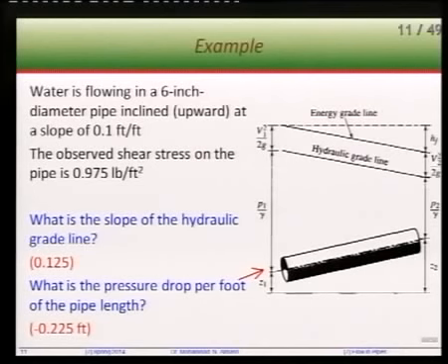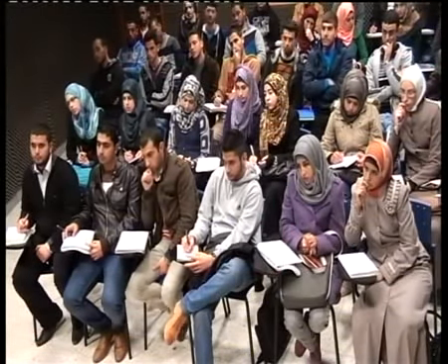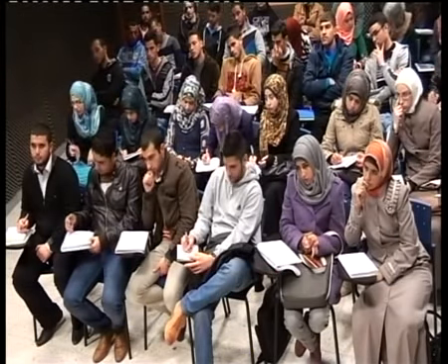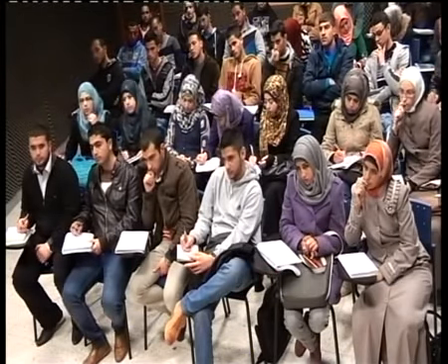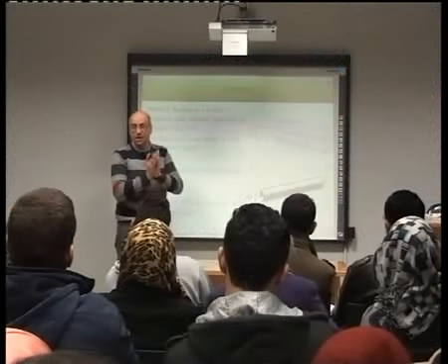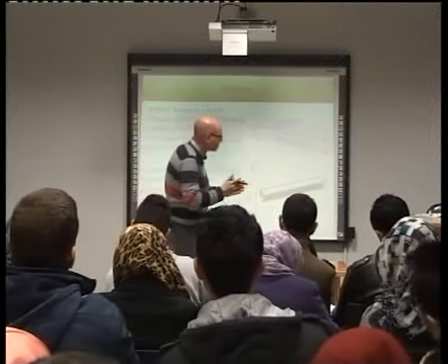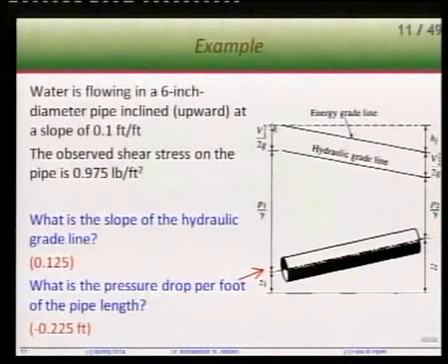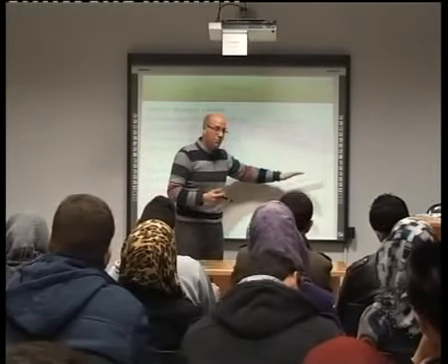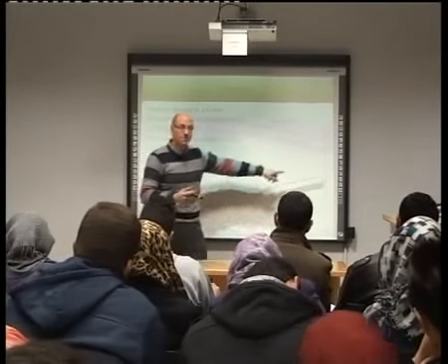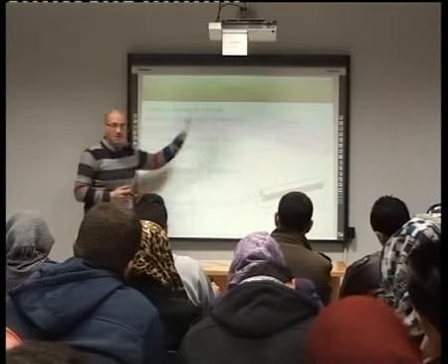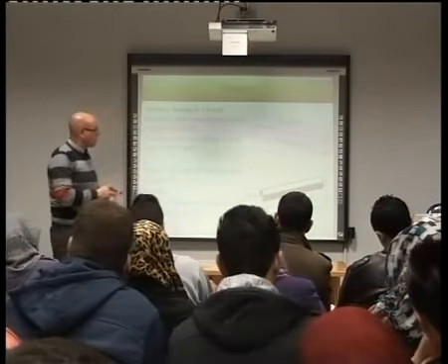Energy. H1 is larger than H2. That means H1 is larger than H2. Or, in a better way to say it, water all the time goes in the direction of losing head. So, if this is the case, that means this point is at a higher elevation than this point. That means this difference was lost or spent for the movement or the transfer of water from point 1 to point 2. So there is no need, in fact, to say the word upward, by the way. So this is one thing.